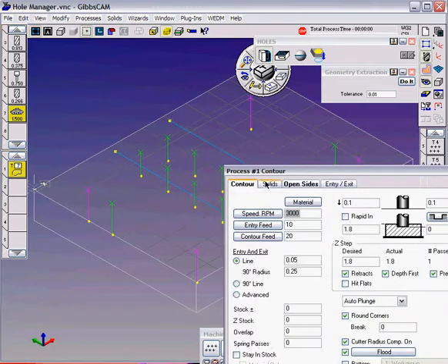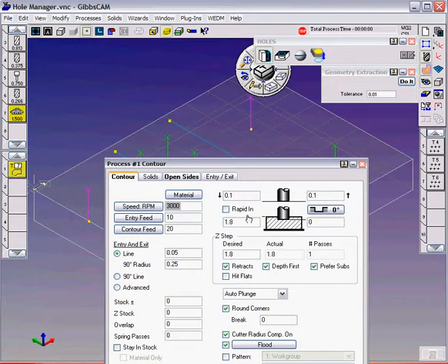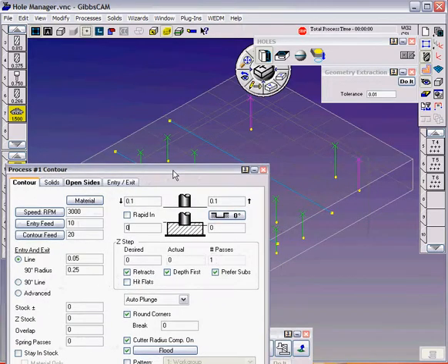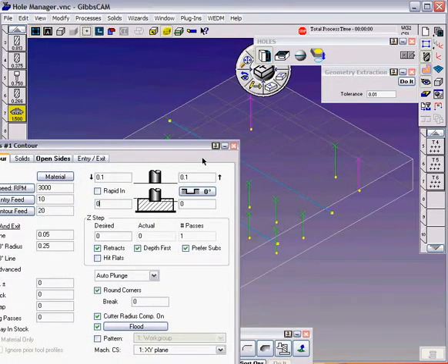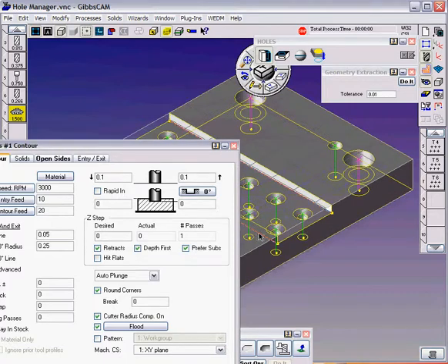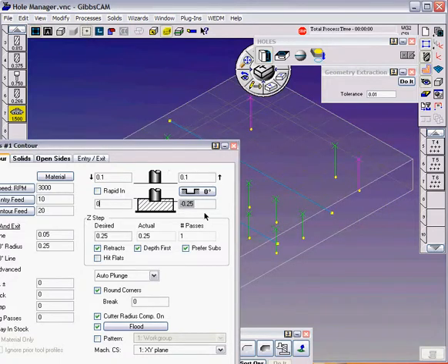And we're going to start at, again, 100 thousandths. We're going to machine from Z0, and the depth of those slots is, I can turn the solid model on. With the depth box active here, just hold down the Alt key and click on that surface. It tells me that's 1/4 inch. I can also do the same thing by clicking on those two features I just extracted. The same thing would be prudent there.